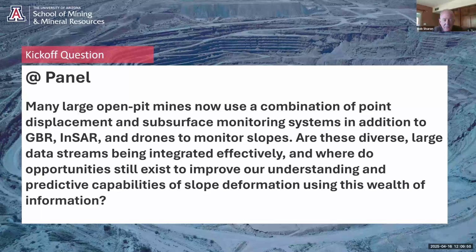So there's a lot of information out there that can be joined, if it's done effectively, to interpret movement, not just the movement itself, but also why the ground is moving. One good example could be if you're getting a lot of rain. The slopes take in rain, and you're getting a response to pore pressure increases that could induce slope movement. If we could bring these types of information together to look at them at the same time, that helps us with interpretive context.